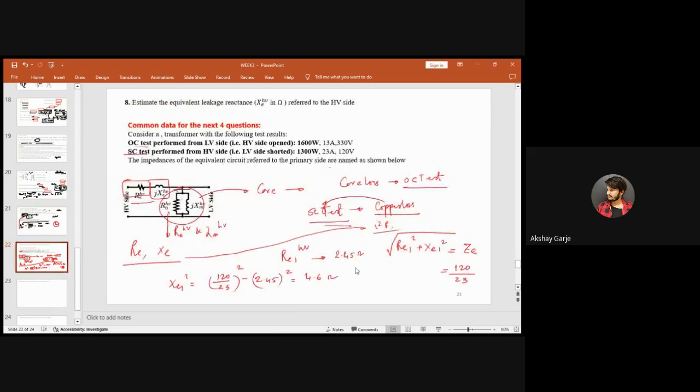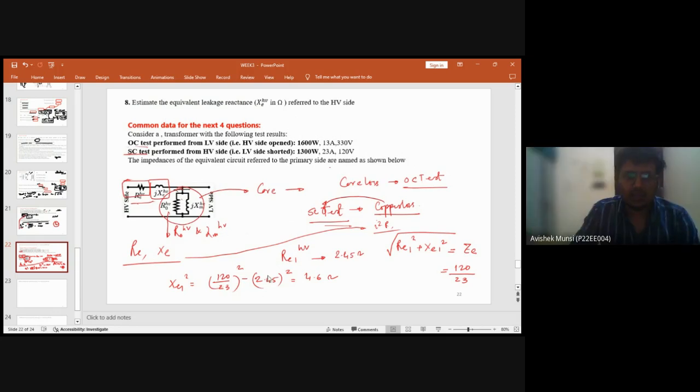So, 4.6 you are saying. That means if it is in the ratio, the losses will increase and the current also increases that way. Yeah. Because from short circuit test, we are calculating copper loss. Copper loss will definitely depend upon I, and that is a variable loss. Because if your rated load is changed, then your loss is also changed. Yes, sir.